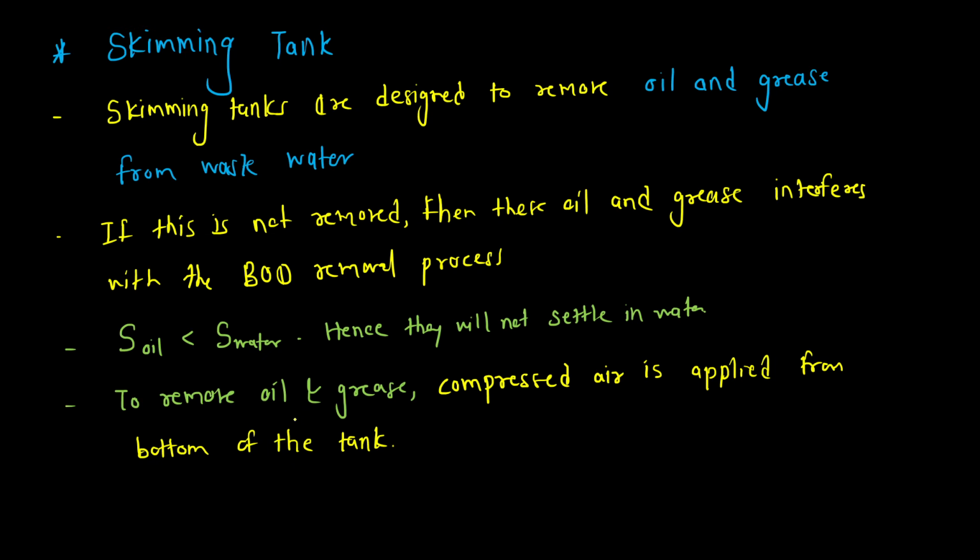Okay, so when this air comes in contact with the oil and greasy particles, they produce a floc, or we can say whatever the oil and grease is present inside the water, it all gets collected at the top surface. As oil and grease has less specific gravity, hence they will be present on the top surface.